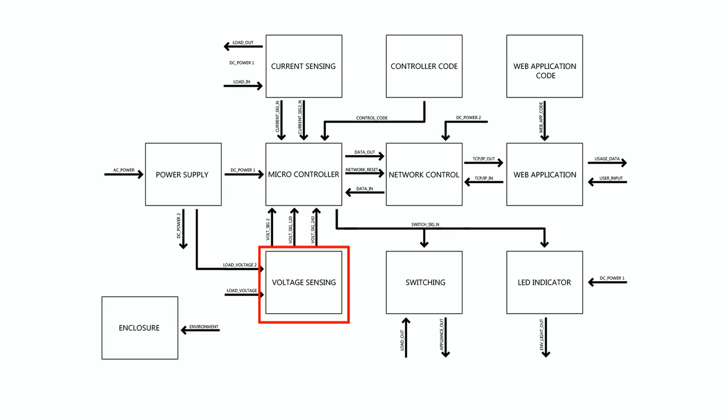The voltage sensing block provides both a voltage magnitude of the devices being powered as well as a phase angle of the house's AC power. The current sensing block measures the magnitude and phase of each of the three devices that are connected. All of this hardware is contained within the enclosure. This enclosure is a standard breaker panel box that allows for easy installation.